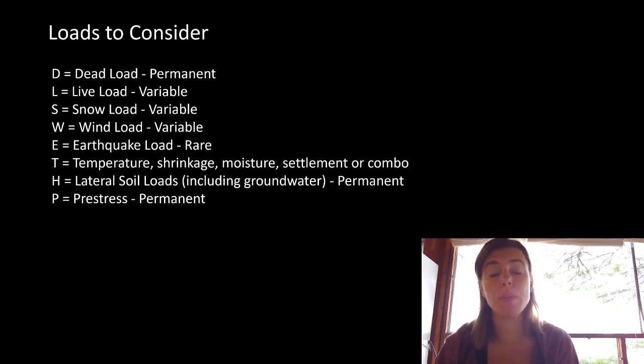In Ontario, specifically Toronto, in the past it had been overestimated for years, and they slowly whittled it down just in time for climate change to really start to have an impact on the snow loads we're seeing in the area, which has increased the snow loads again in the past couple code iterations. Wind load is variable.